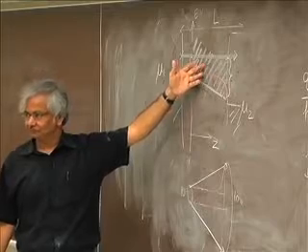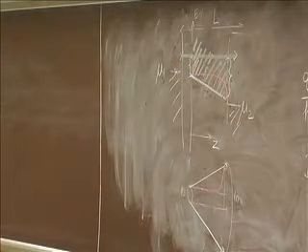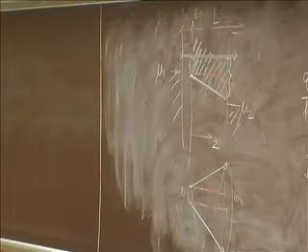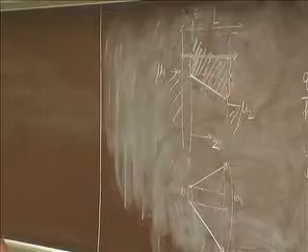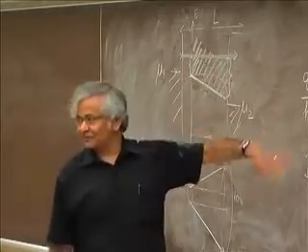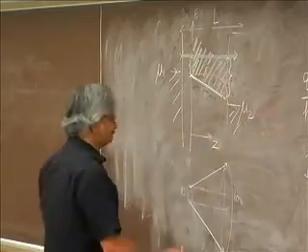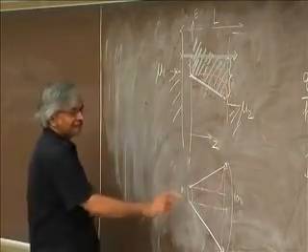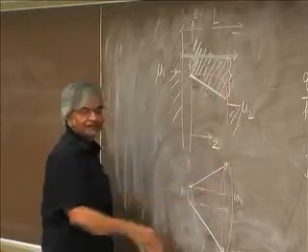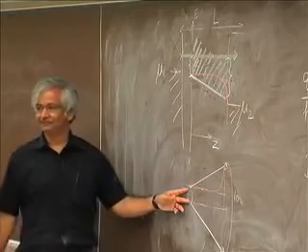Are you assuming scattering is occurring, or not? Because this argument requires scattering. If you had a ballistic transistor, none of this would matter. If you had a ballistic channel, that is of course one important point, then the fact that you have 100 modes here makes no difference. Finally, the conductance is limited by the 10 modes.